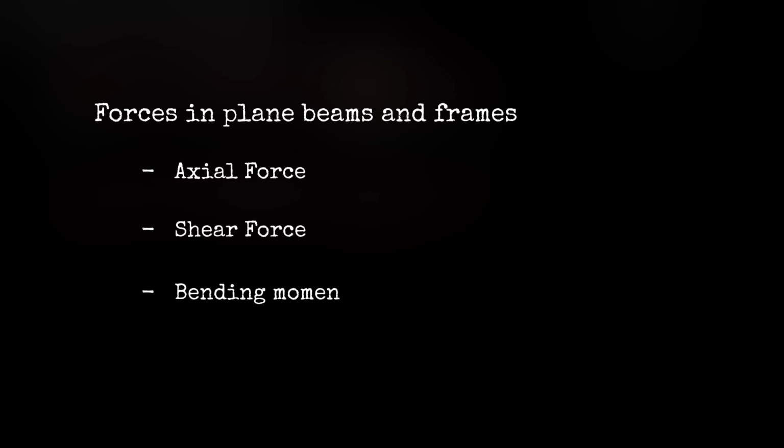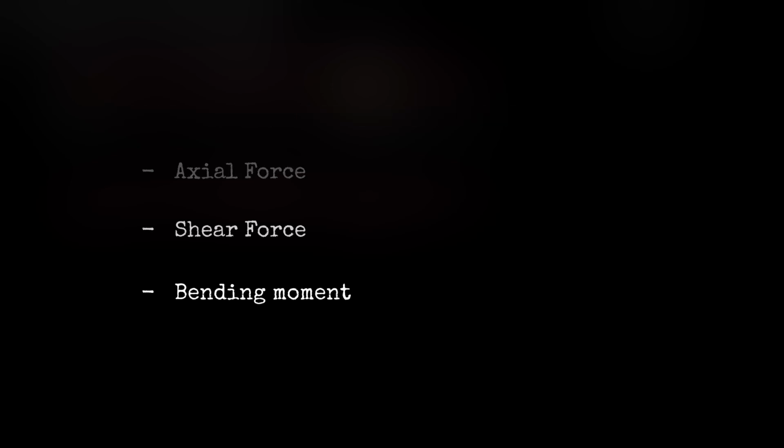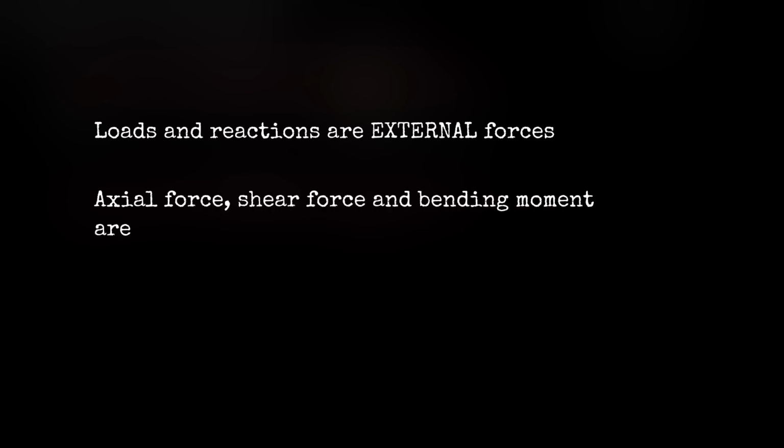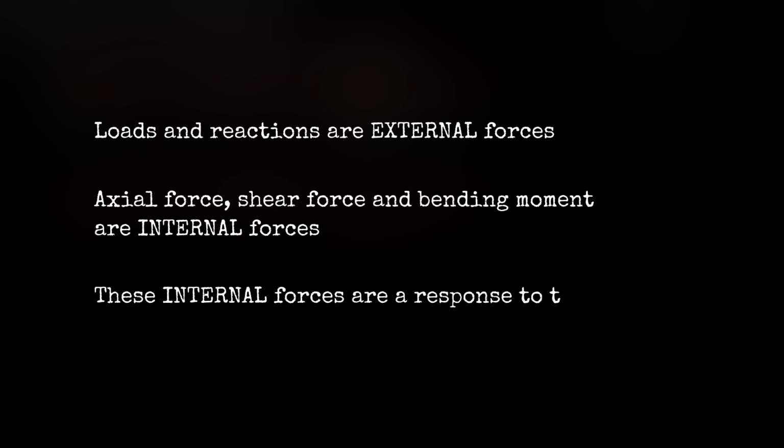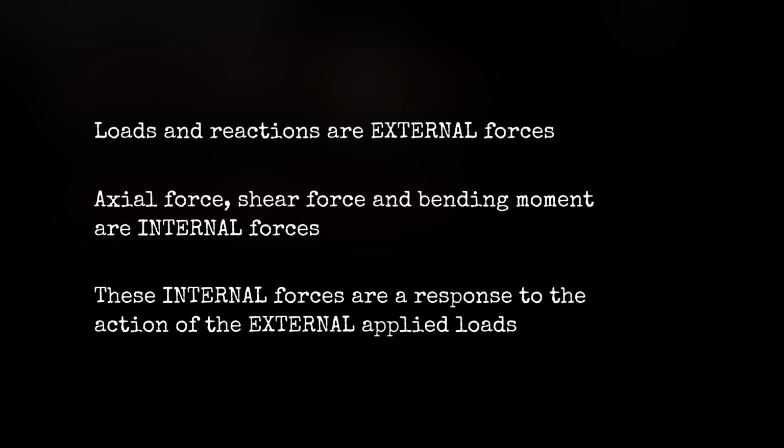And if you want to see a more detailed video on finding reactions, then click on the link on the screen. In general, plane beams and frames carry axial force, shear force and bending moment. These forces arise in the structural members in response to loads applied to the structure. Dr. Jim thinks of loads and reactions as external forces, and he thinks of axial force, shear force and bending moment as internal forces that arise in response to the external applied loads.